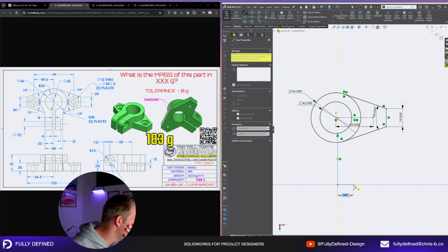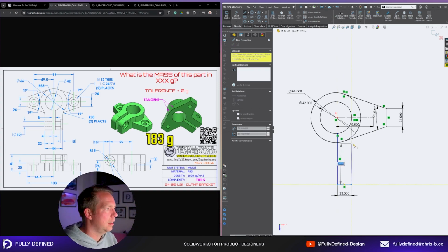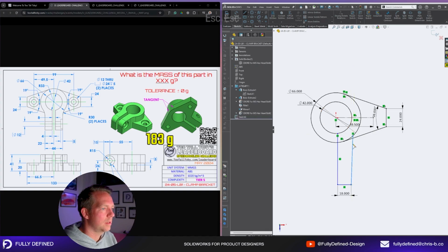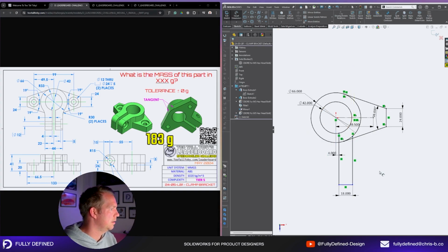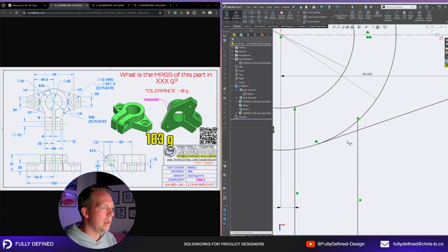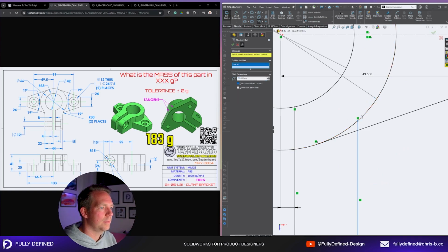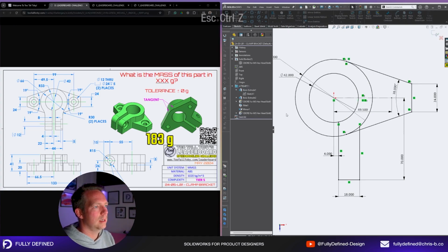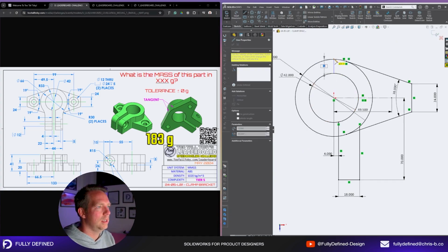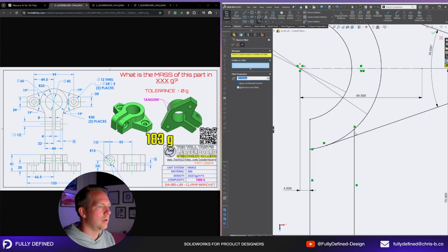Now I know that gap is 4 and it's 22. So that makes that 18, and that's got to be vertical. I'm just thinking through one of my issues here, and that length is 70 from the middle. All right. Right now though, can I fill it between that and that line? No, because it's not trimmed. And if I trim that now, I lose that center circle there, so I have to do a line here. Then I can trim, and then I can radius.